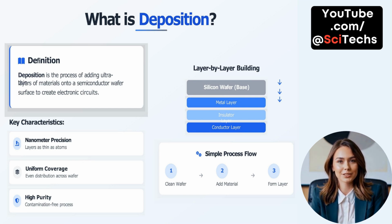Key characteristics include nanometer scale control for extreme accuracy, uniform coverage across the entire wafer to ensure consistent performance, and high purity, meaning the process is nearly free from contamination. The deposition process itself is straightforward in concept. First, the wafer is cleaned. Second, the desired material is added. And third, a uniform and functional layer is formed through precise engineering techniques.